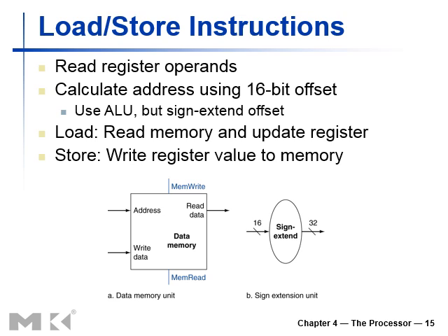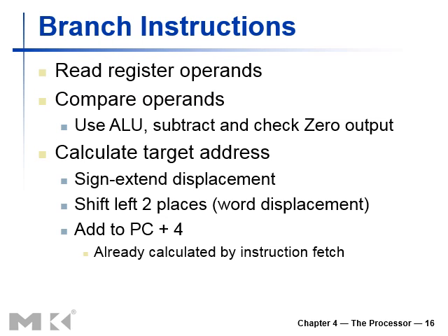We will continue our discussion from this slide onward, and let us see how we're going to design that. But before that, we're going to see the requirements for the branch instruction. We've seen that the branch instructions are the conditional instructions that have the capability to change the sequential flow of execution of your program. And how are these instructions being processed? Basically, first of all, we have to read the operands, and definitely we have to read the operands from the register file.